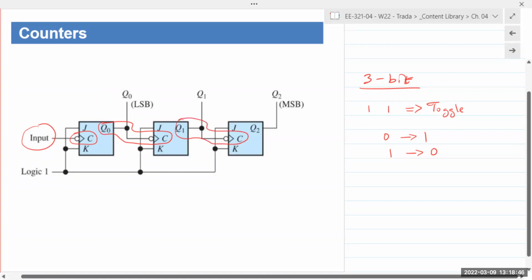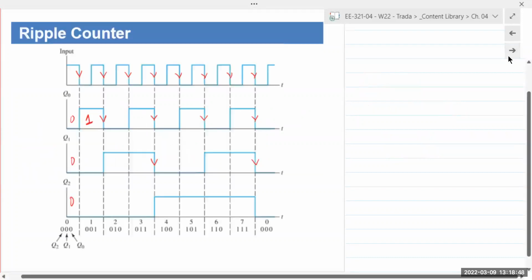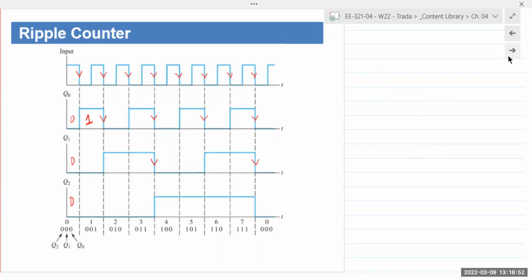These are building blocks, right? You can take these building blocks and design circuits however you want, and this is another way of using the features. Again, each flip-flop will only activate at the negative-going pulse. Whenever it receives a negative-going pulse, it activates, and the mode of activation is that it flips from 0 to 1. Because it's cascading, when you first give an input, a negative-going pulse, the first one changes and toggles its value at every negative-going pulse.